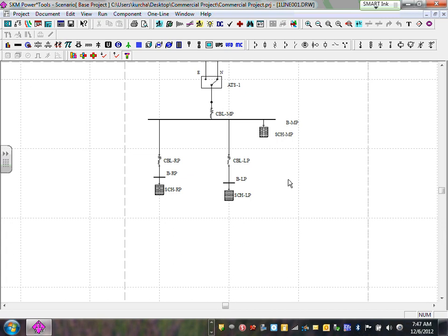If you guys remember yesterday when we were looking at the riser in Revit, the circuit breakers for the lighting panel as well as the receptacle panel are located in the main panel because we're using main lugs only. So I can't put my circuit breaker here, right? Everybody understand? I can't put it here. It has to be way at the top right here, right? Everybody understand why the circuit breakers for the lighting panel and receptacle panel have to be in the main panel? Because that's how we design the system.